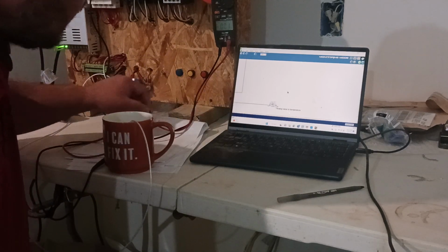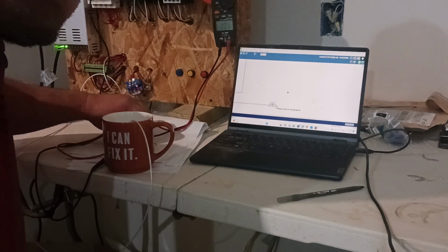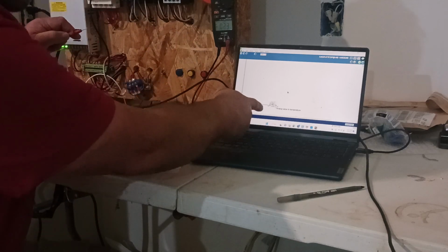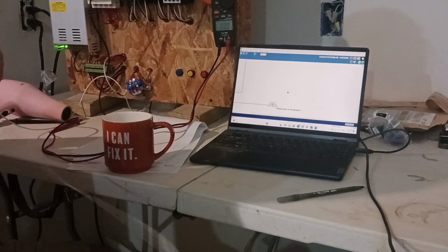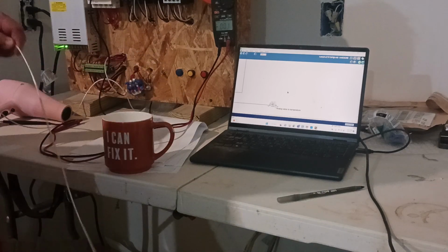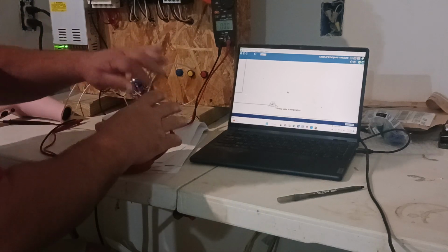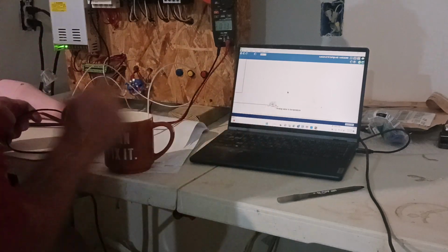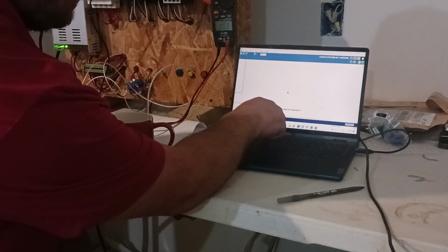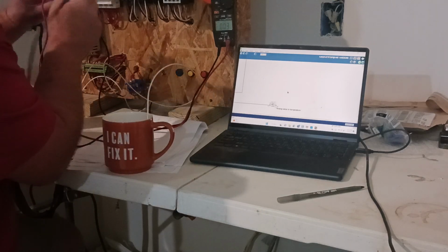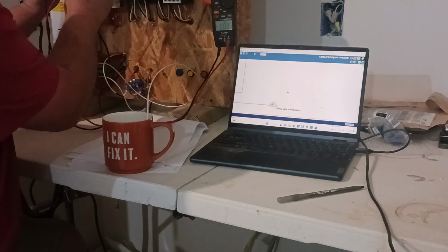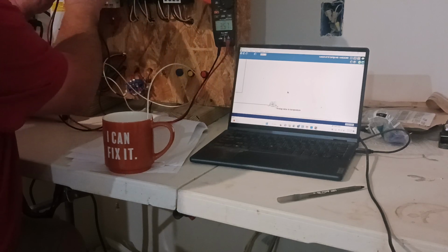You see how it went down to 93 and 92. See my temperature, it's going down. This is my analog value. Oh, I lost my little temperature sensor out of my ice, so it'll go back up temporarily. But if I can keep it in the ice, you'll notice these two values will be going down. This is my analog value that the PLC sees, and this is my scale value that tells you what temperature we're basically at. And I can put my meter on the analog channel, and you can see